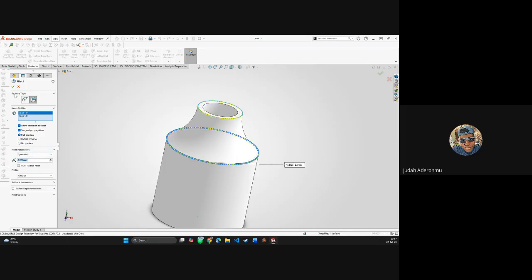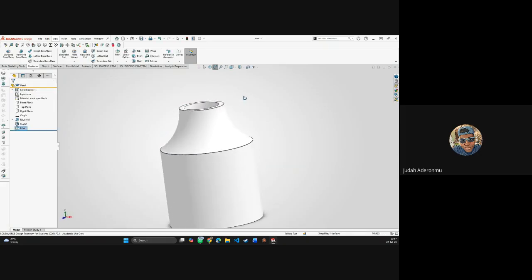The fillets are hardly even showing, but you just make sure that there's a fillet so that it doesn't hurt you. See, for example, now it still looks like a normal edge, but it is filleted. So if you were to 3D print this and brush your hands across this edge here, it's not going to cut in.